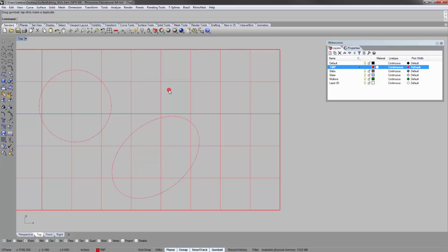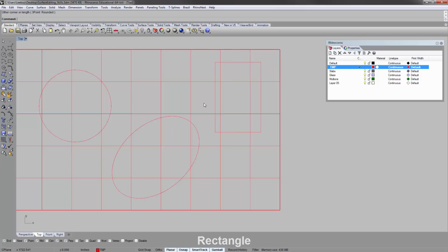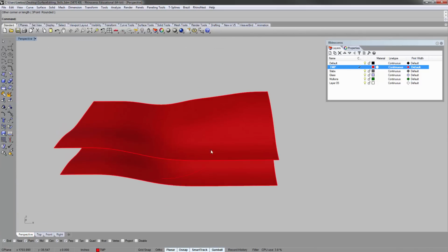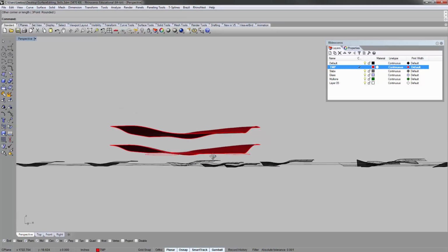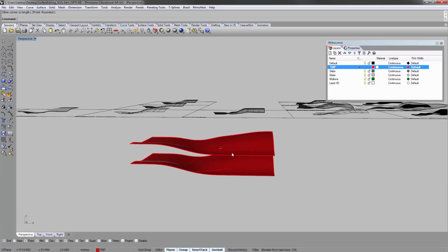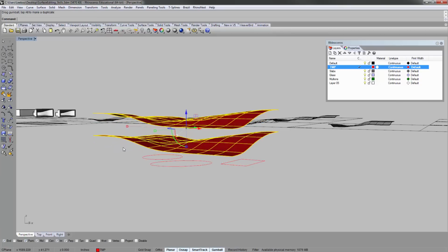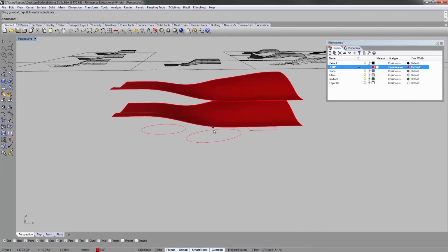Now let's make it a little larger, something like this. And then a square somewhere. Let's do it there. Now note I'm being careful not to snap to the surface, so I'm clicking in empty spots. The reason being, eventually I want these things to be on the ground, right? I want them to be on the XY plane. And now these two, I'm just going to move them up. It doesn't matter, arbitrary distance. Okay? All right.